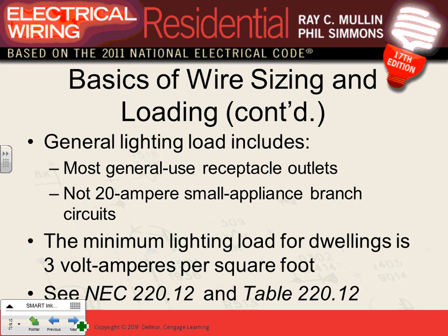General lighting and receptacle. Now let's go back to the loads. Let's go back to the dwelling. I want to remind you guys, if we're doing a commercial building, we don't even think of a 15 amp branch circuit. Get it out. 20 amp is your minimum. It's not worth putting a number 14 in a building like Dunwoody. 20 amp is your minimum for branch circuits, receptacles, and lights. Just keep this in mind.